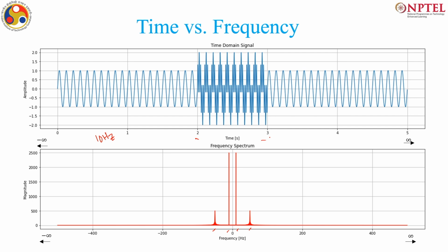So, in this duration we know that this is not just a 10 hertz signal, there is something more to this 10 hertz signal, but we do not know what frequencies are there. So, the frequency spectra is telling me what frequencies are there, but where they are, I do not know. But the time domain is telling me that there is something, and where it is I can understand, but what frequencies I do not know. So, just knowing one version of the signal may not be sufficient to get a clearer picture of the holistic thing, and this is often what happens in the real world.